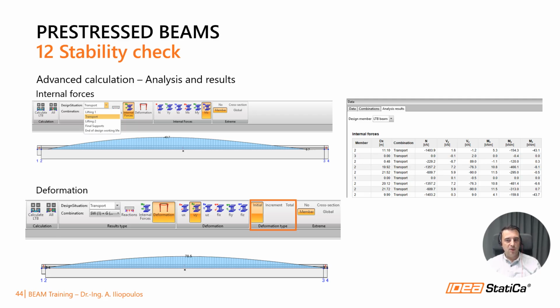So let's talk about the deformations a little. At the first step, the beam is deformed into a parabolic shape using the value of the initial imperfection. Then in this shape it is mounted on hinges. This causes an initial rotation, so the center of gravity is below the roll axis. So this is the initial deformation.